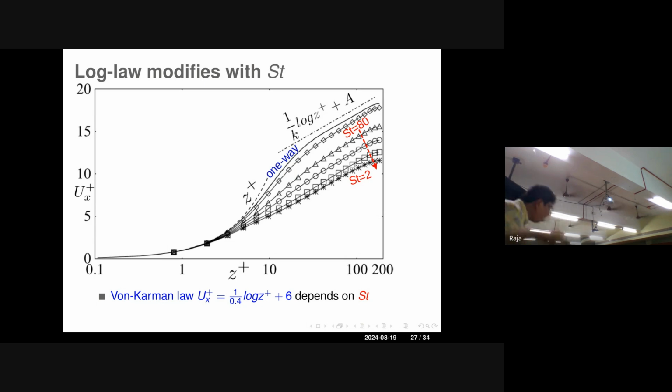And normal to that wall, that is what we are trying to look at. Typically this unit 200 means we almost reach the center of the channel. So from all the way down to the center of the channel, this is the way we have to do it. These are not periodic but outflow conditions. Whatever structures come, let them go. But synthetic turbulence enters every time.